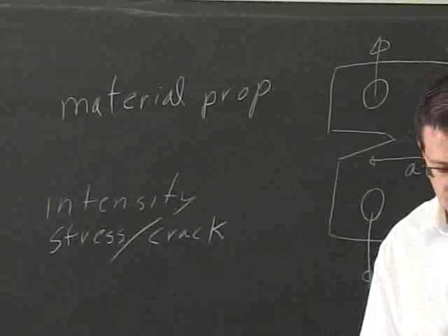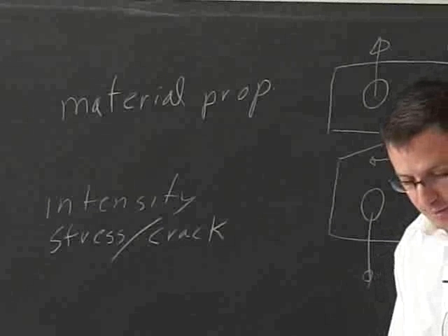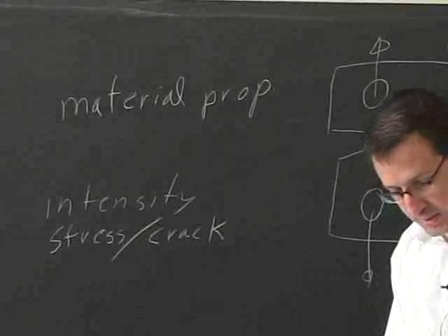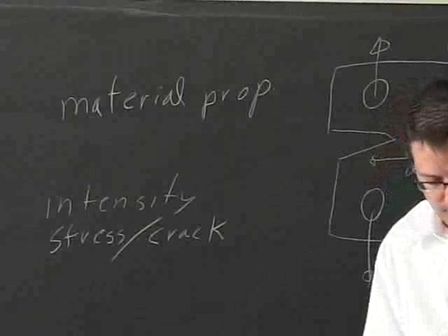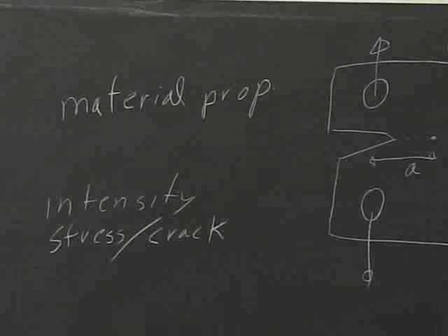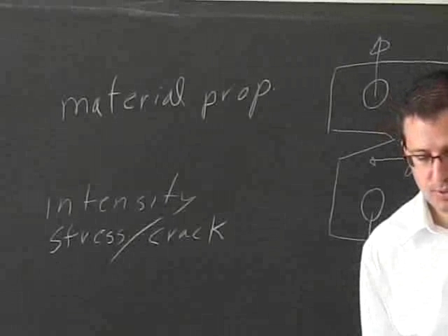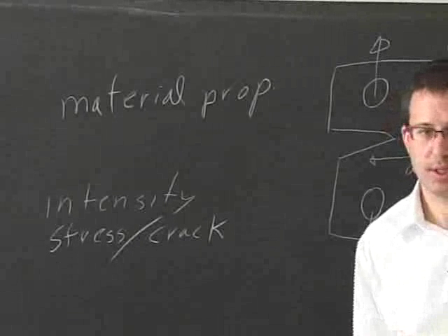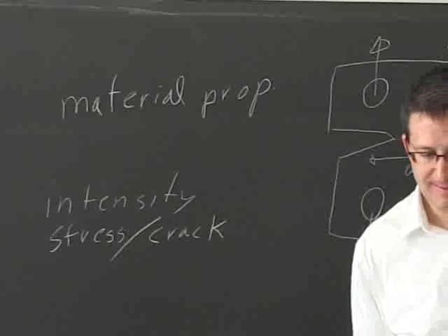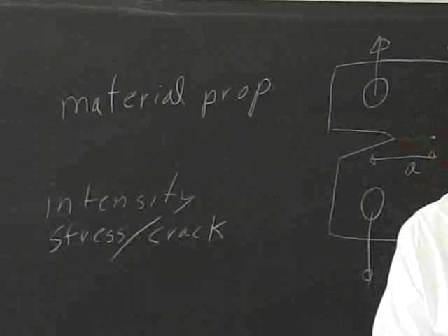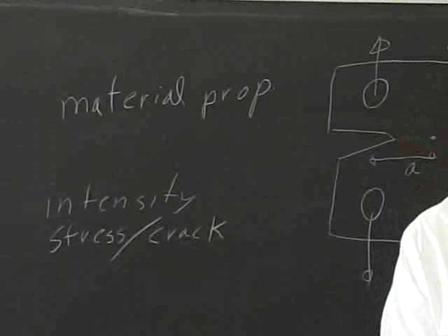So if you have an assembly, you say, I want it to last forever. That's where we talk about endurance limit. That was actually 10 to the 8. But a lot of times we have the fatigue limit, which is at 10 to the 7, in a case where you don't have a plateau here on that stress strain curve. So I think in general, you don't necessarily have to design for a fatigue limit.